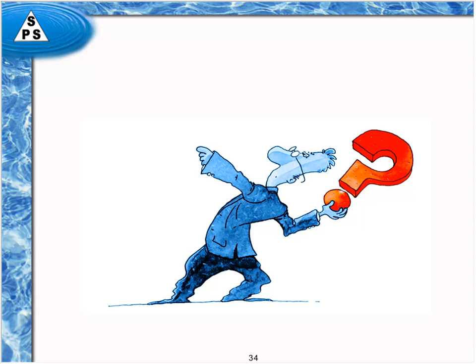Sometimes it's just organic molecules that impinge on the surface and biofoul the surface with an organic residue that's not living. And so you still have to clean the systems on a periodic basis, but I think you're going to find the cleaning less necessary if you sanitize more frequently rather than less frequently. But again, daily to weekly is pretty typical.